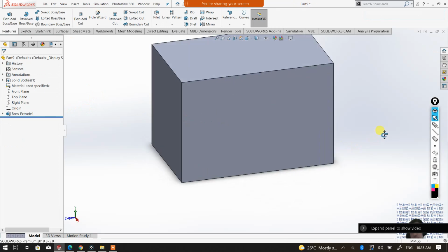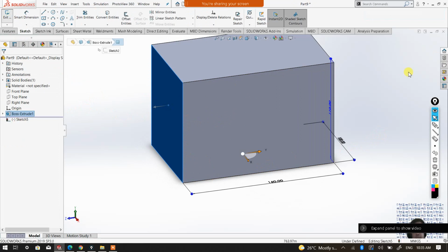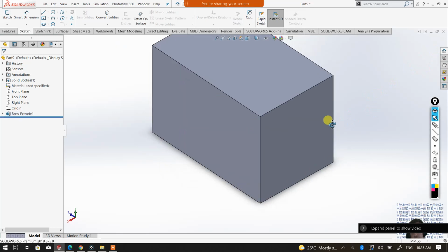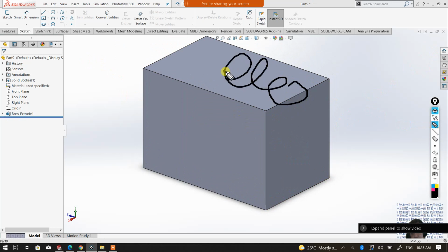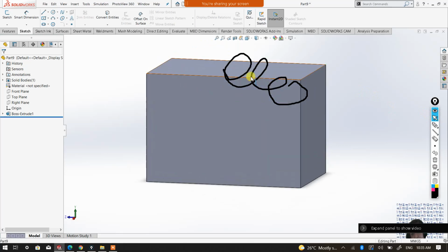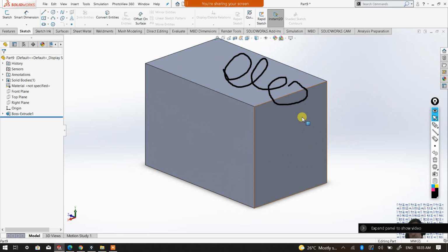Let's say for example I'm going to pick this surface as my sketch plane. Oops, sorry, this is for the profile. Sorry ladies and gentlemen. Why did it say zero profile earlier? Because when I make the twist, we make it upward, so it will turn upward, and some parts will stick out, like this for example. When it sticks out, it will create zero thickness, so it can't work. In that case, we can only do it on the inside, for the extruded cut.